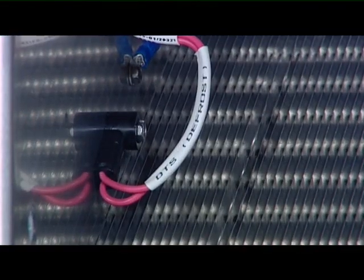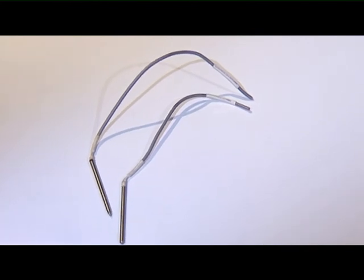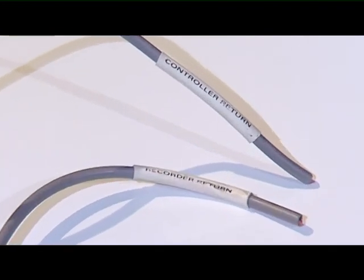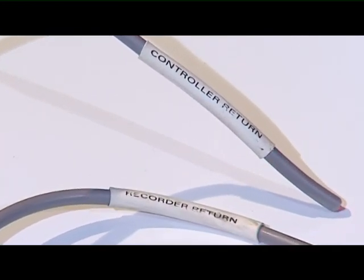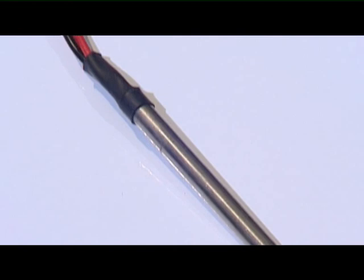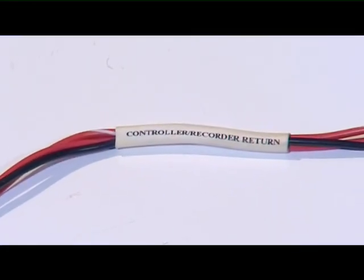Defrost sensor. Return air sensors. Microlink units are fitted with 2 return air sensors. One sensor is needed for recording data and the other one to control cargo temperature. On some units, the 2 return air sensors are replaced with one sensor called a combi sensor.